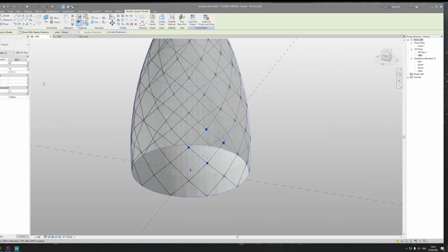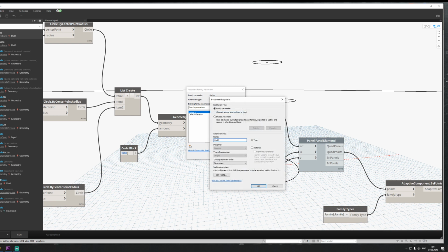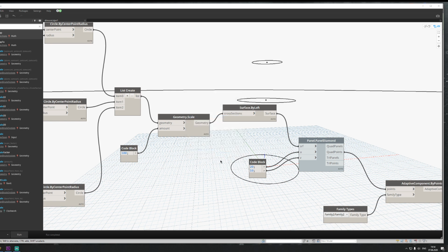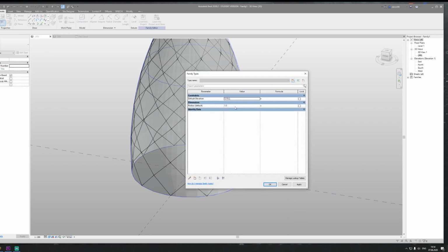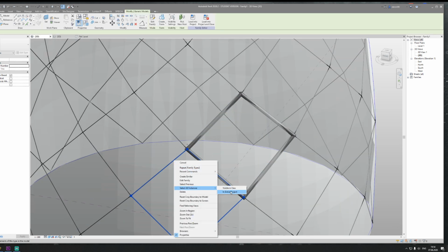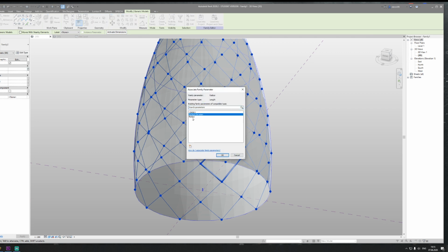And everything is alright. Yeah. I will make the offset. This one, radius. Not like an instance. I will create one more parameter, radius. You can create it in Dynamo if you want, or you can make it in Revit. I will use the Revit way. I think this is the better one for us for now. I will go to the creation, and here the radius, and I will say 10. Apply. And as you can see, here is the 10. Actually, I need to select all of them inside the project, and I will say the radius, use this parameter radius.